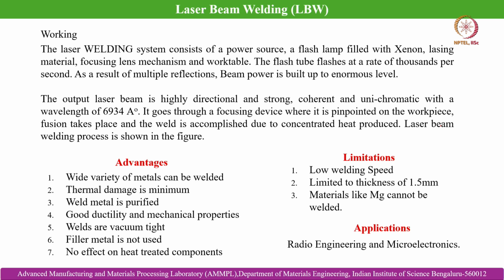If you recall, we discussed earlier that in fusion welding it is the heat affected zone which is the weakest link in the joint assembly. Because of the focused nature of the laser beam, the heat affected zone size is minimum. So overall it gives improved mechanical properties in the weld zone and also in the base metal adjacent to it.